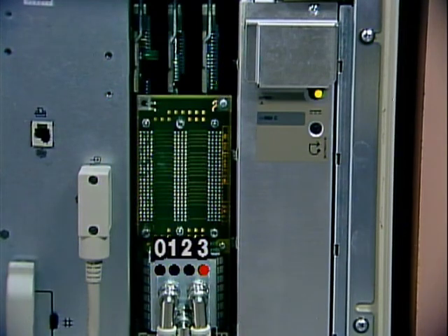If LED number 3 is off while the green LED is off, the remaining 3 LEDs will point out the likely bad module. Starting on the left, when LED number 0 is lit, it indicates a faulty base module. When LED number 1 is lit, it indicates a faulty output module. If LED number 2 is lit, it indicates a faulty expansion module. If LED number 3 is off and more than one of the other LEDs is lit, the problem could be in either of the corresponding modules. If the system indicates a graphic subsystem failure and all LEDs are off, the problem is usually caused by a faulty front plane or improper seating of the front plane.